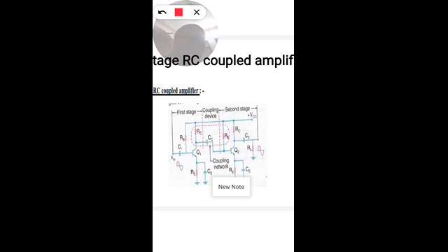So whenever there is an increase in the collector current with the temperature, the operating point shifts, moves up in the DC load line when IC is increasing, so the operating point moves slightly above the fixed value. In general, the operating point is fixed in the middle of the DC load line for faithful amplification.